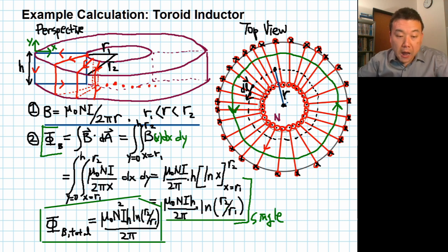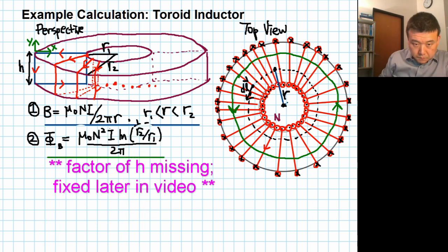So now we are going to use this expression for magnetic flux to figure out an expression for induced voltage, and from that calculate the inductance of this toroid. All right, so we have the magnetic flux. This is the total magnetic flux, as you can see in this n squared.